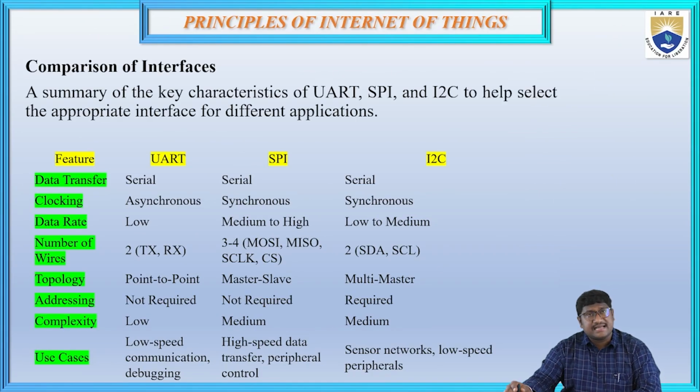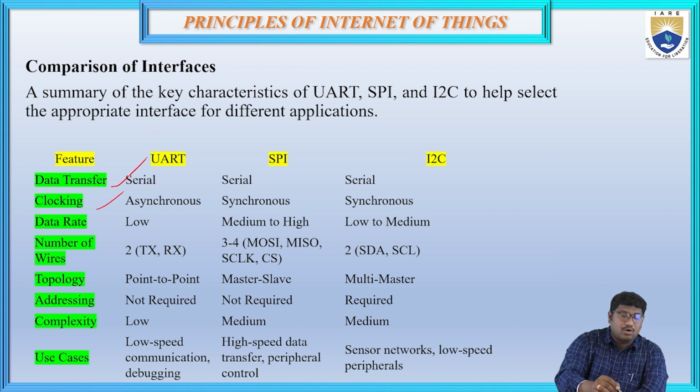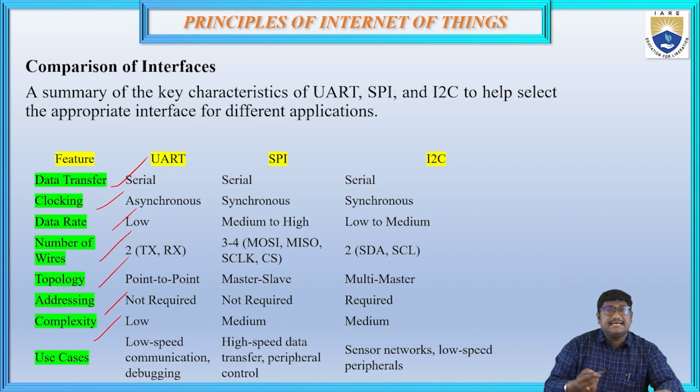And now I will show you a comparison considering multiple factors such as data transfer, clocking, data rate, number of wires, topology, addressing, complexity, and use cases. See here how the data transfer is done in UART, SPI and I2C.